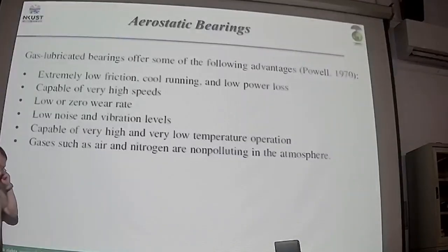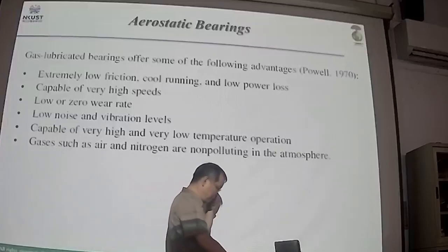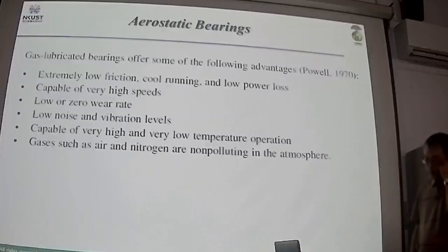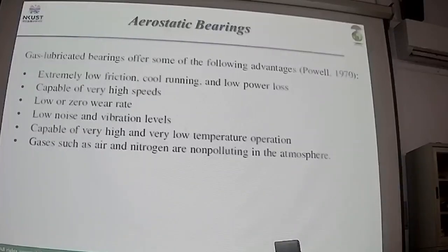So here are some of the advantages for the air bearing, aerostatic bearing, especially if you need to operate at very high speeds or with a very small runout. Then you need to choose your system with aerostatic bearing instead of hydrostatic bearing.